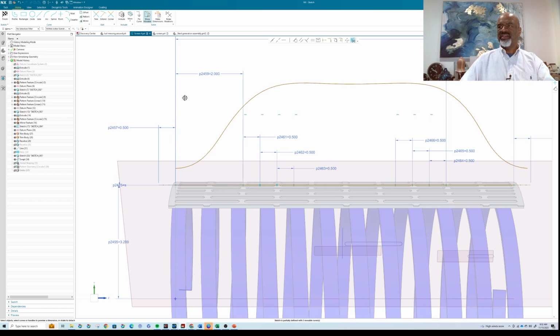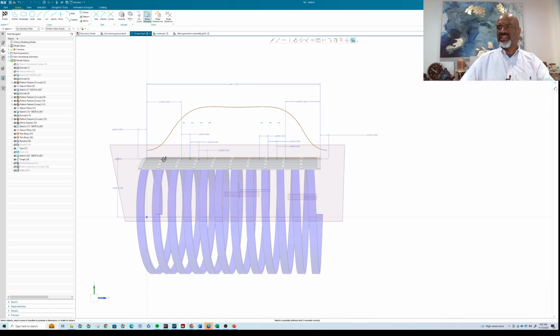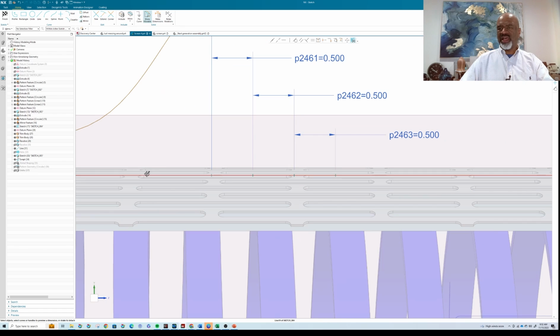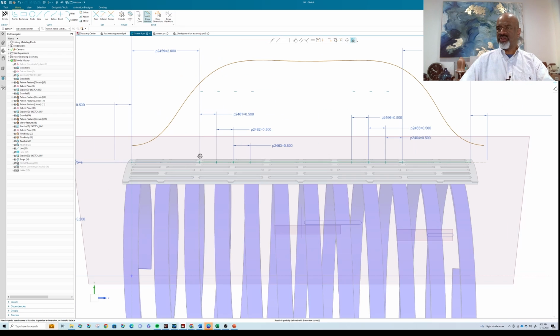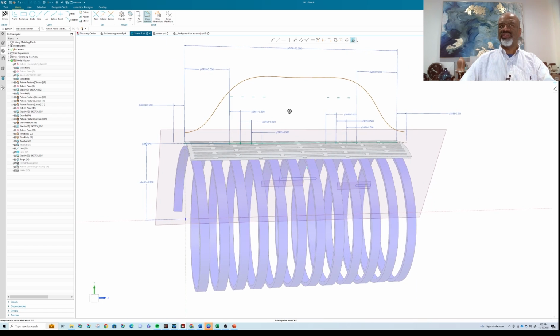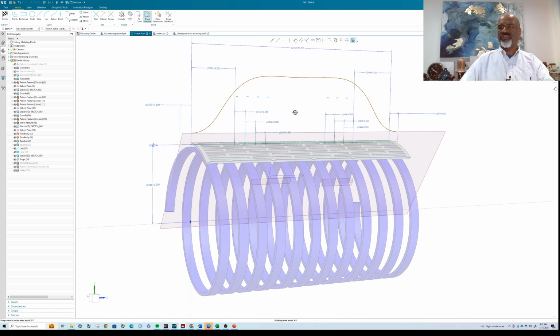And when I increment that variable S, it lifts these 4 points and forces the spline that goes from here to here into a shape that looks more like this, you see? And I use that spline to make a surface.